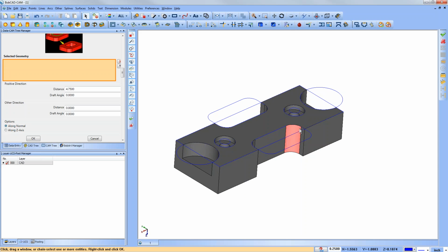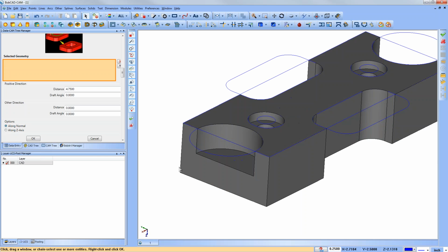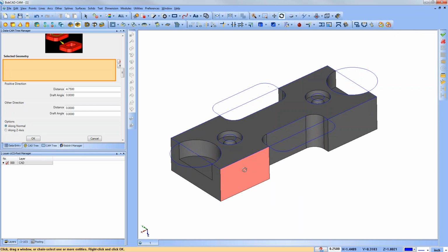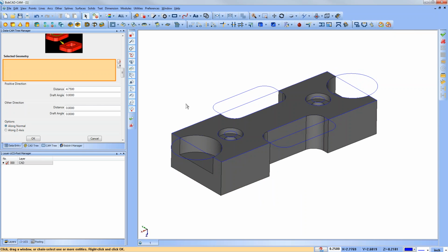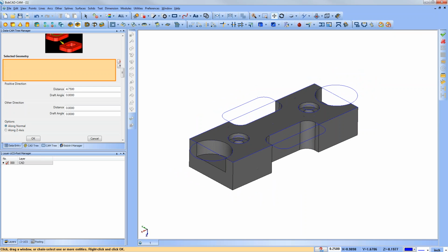So here's something that we have, a completed little part, kind of a simple part, but I think it shows a few of the basic steps to create a solid from 2D wireframe. So if you need to have a solid model, you can do it pretty quickly with this extrude boss and extrude cut. I'm going to show another example here in a minute of using it on different planes. So for instance, the layers that I mentioned earlier. The idea here is organization. I've got this busy part here with some geometry.